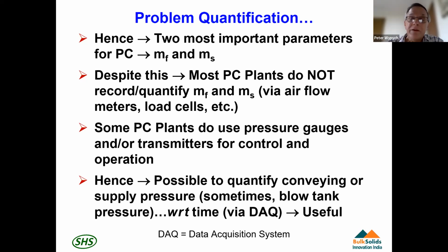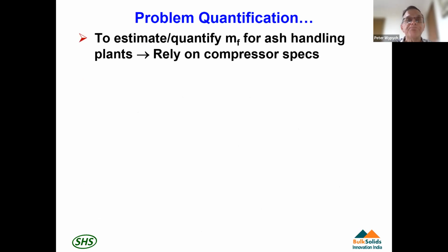And of course, if it's different, then you have to see if the first one's wrong or the second one's wrong. So it's always an issue that we have to check. So don't ever assume a pressure gauge is reading the correct value. But anyway, once we get our pressures confirmed, and if we can record that off a data acquisition system, say through some sort of control system on site, then that sort of pressure history is very useful indeed. It gives us an idea, a picture on how the system is performing.